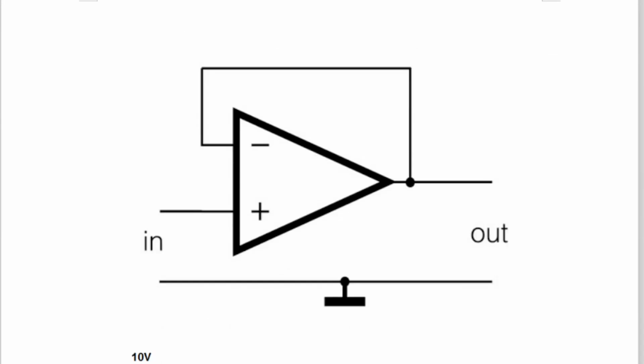Now there is one more application of the op-amp which you know, in which the output is directly fed back to the input. No feedback resistor. RF is not there, so RF is as good as 0, and input is applied at the non-inverting input. Whenever you apply input at the non-inverting input, it is used as a non-inverting amplifier, but the feedback resistor is 0.